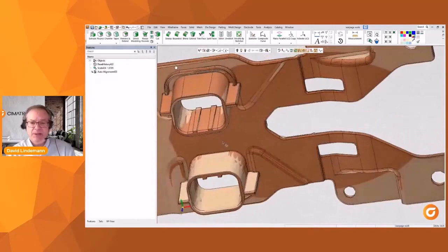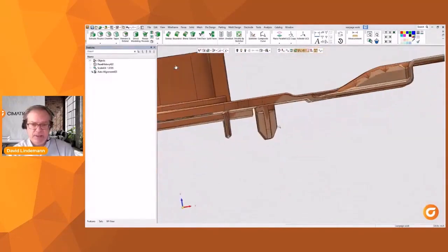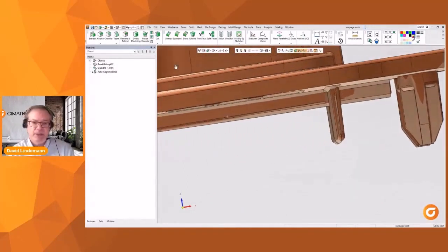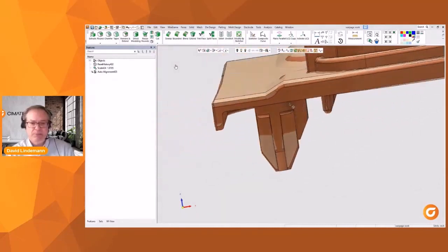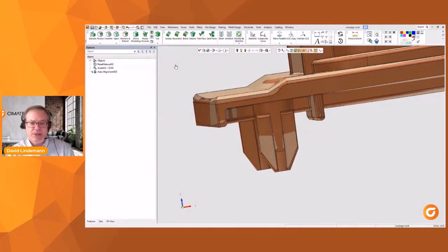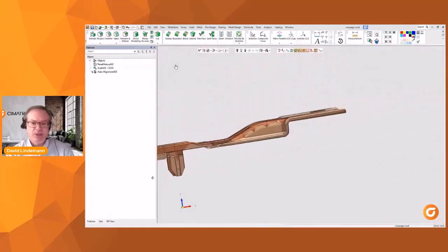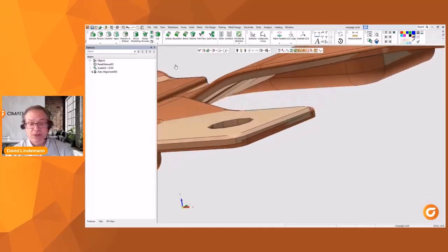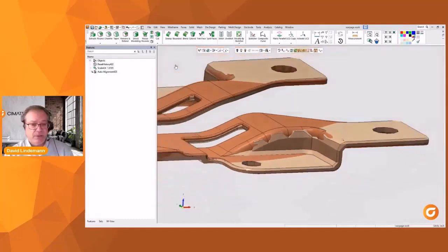And just comparing the lighter colored STL file to the darker colored CAD file, I can clearly see the deviation now. Where it bleeds together is close, but boy, you can sure see it bowing here on the end. You can see that those posts are bent out, and the warpage is kind of pulling the edges in towards center. So what was once straight isn't looking straight anymore. Out here on the ends, it looks like that STL file is twisted. So there's a bit involved here.